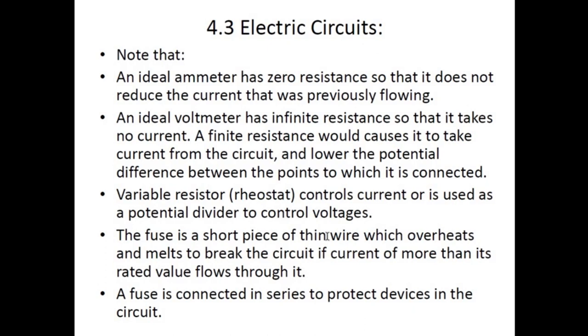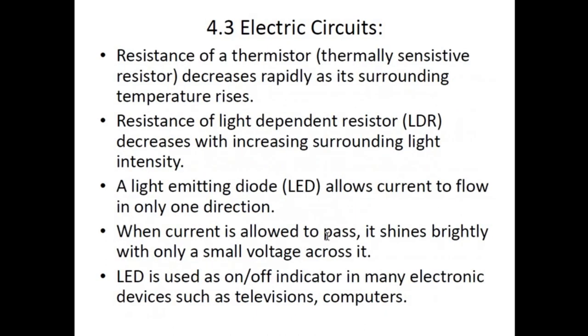A fuse is a short piece of thin wire which overheats and melts to break the circuit if the current is more than its rated value. A fuse basically consists of a thin wire, and if a greater current flows through it, then it becomes heated up and it melts, breaking the circuit, protecting the components that are connected in that circuit. A fuse is always connected in series to protect the devices they are meant to protect.